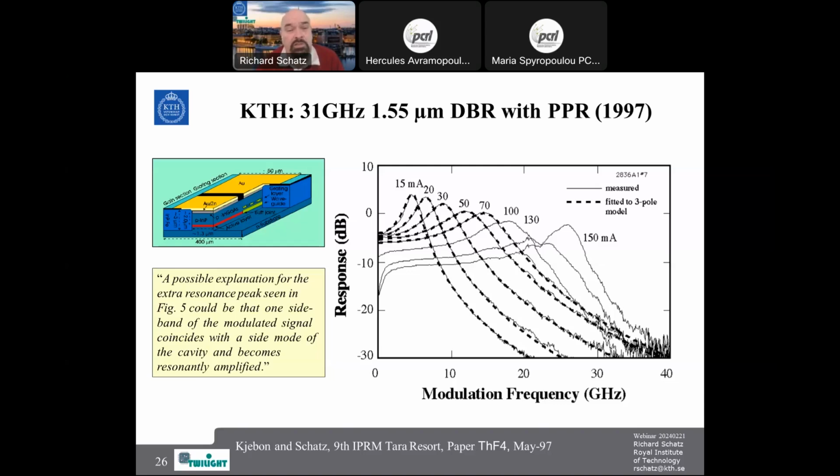But it's possible to use an intracavity modulator and utilize this effect. For pure EMLs, there is no use here. For a pure EML, you just want a laser that has large power, and the bandwidth of the laser itself is not important. It's just the bandwidth of the modulator that is important.